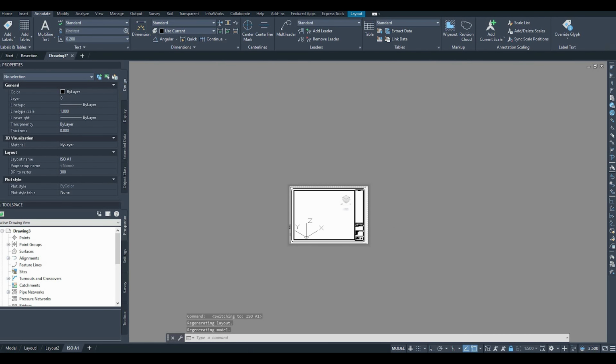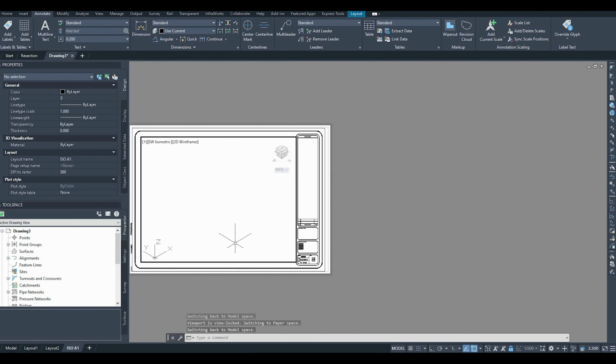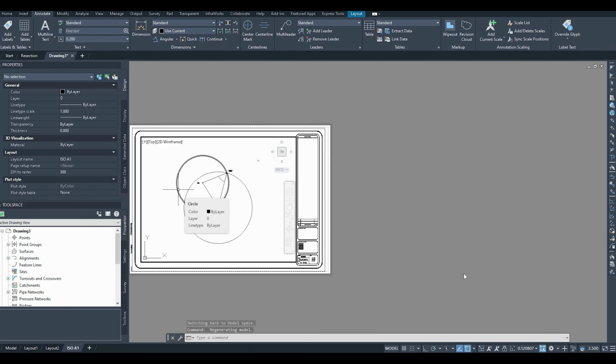And then I can come here to my template, and this is my template. Okay, as you can see here, it's empty now, nothing in there. So from the bottom bar here, guys, go here to this lock logo here. Can you see this lock logo? Just one click to unlock it, yeah? And then you would come here now to pick the top view. Okay, now you can see your drawing.